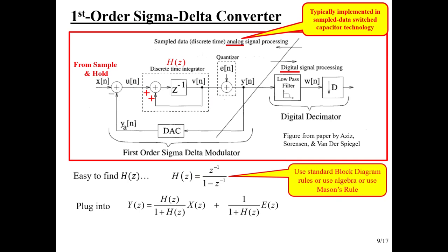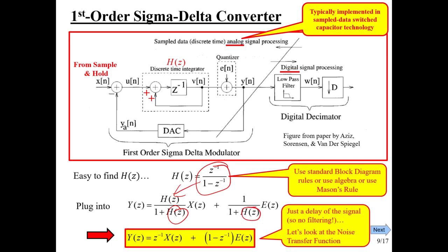So now this is what's going to go in here, here, and here, and we can analyze what ends up happening. So if we literally plug this in here and here, we end up with it boiling down just to z inverse. So it's not quite 1, but it might as well just be. All it does is delay the signal by 1 sample, and that's perfectly fine.